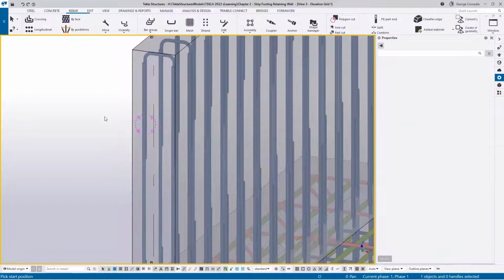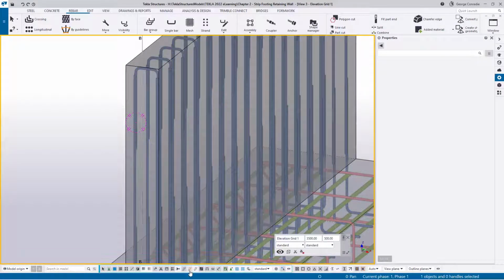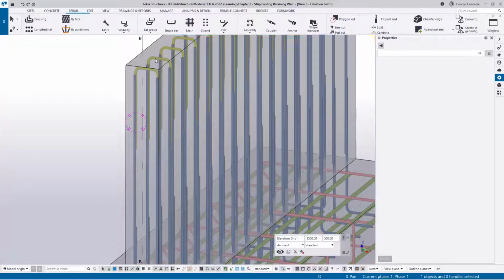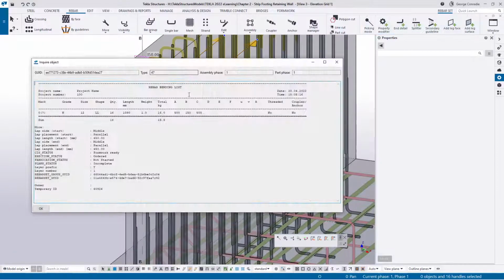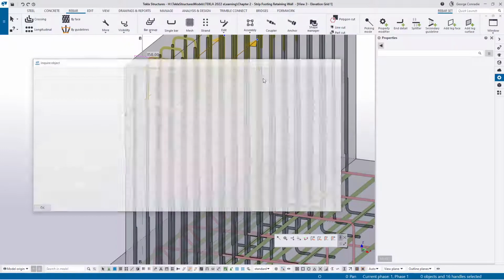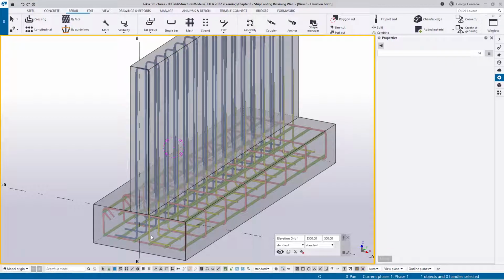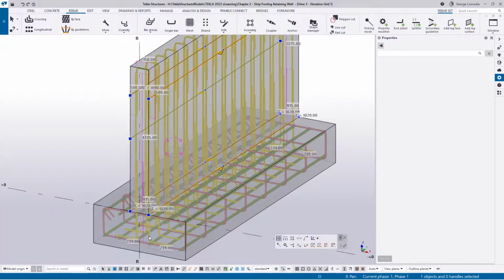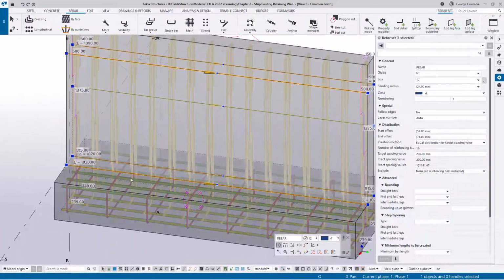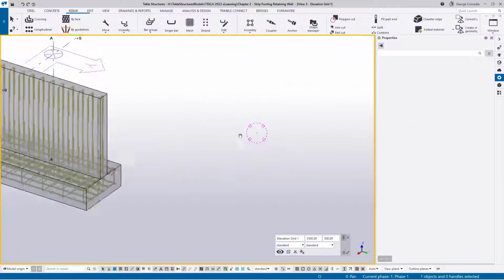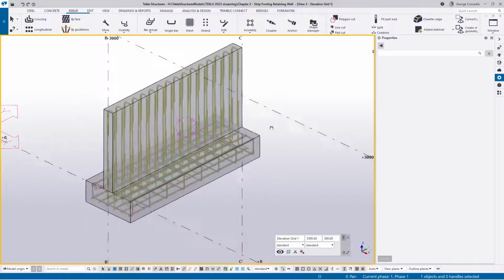So now if I go out here and I select down the bottom here the enable a group in a rebar set, and I click on the use, right click, inquire, we can see we have two 500 legs exactly with 150 in the top. Now we've done all of that with a single bar, and this is still single rebar groups. If I just go to the sets again, you can see it's still a single rebar group, although we've got it broken up into three different parts.